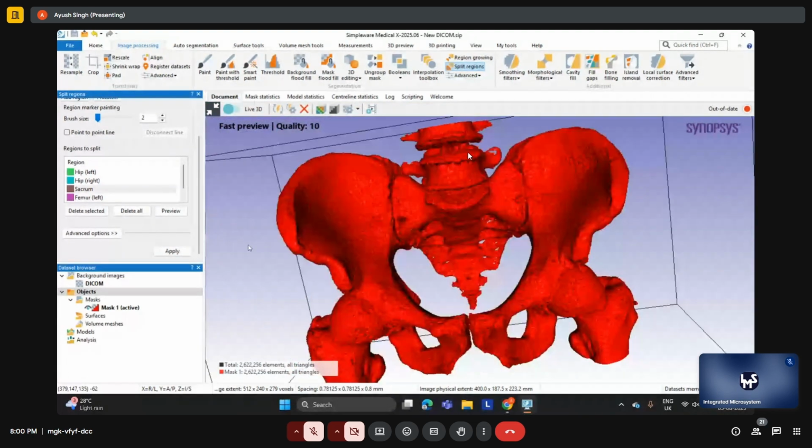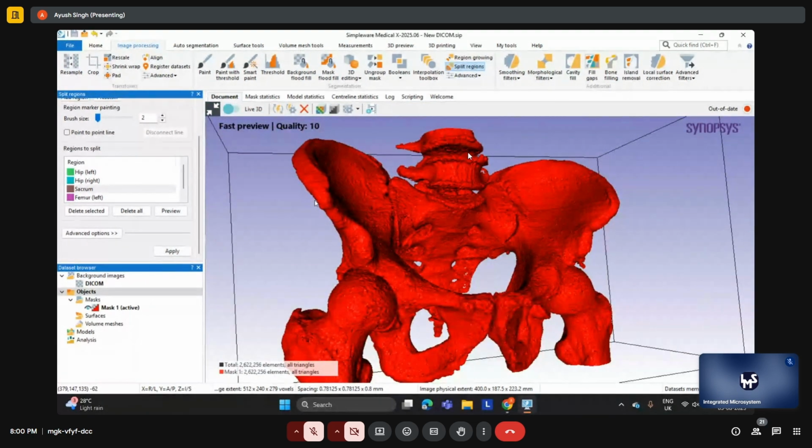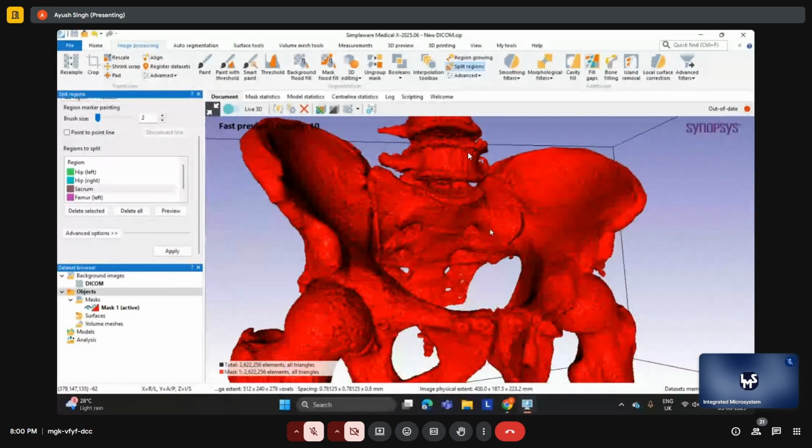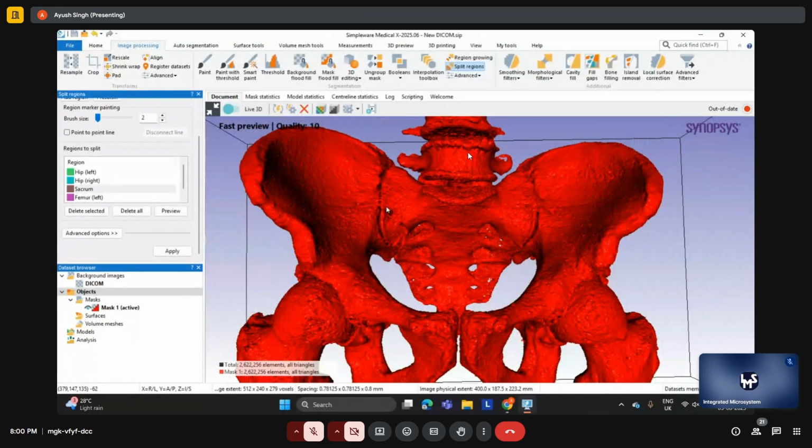We can directly visualize how the marking looks. And this works on the watershed algorithm. Whenever we split different masks from a whole single part, it uses the nearby watershed algorithm to check the grayscale variation, and at the boundaries, it just splits up the part.